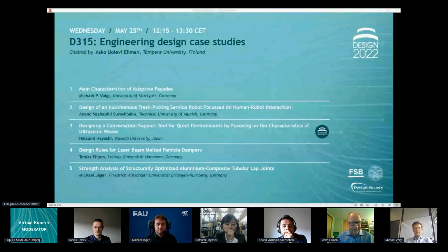Can you explain what is actually the research question of this paper? If you're using CFRP tubes, most of the weight is located at the joints. When you have to join these CFRP tubes together, you have to use a very labor-intensive manufacturing process if you want to laminate them together, or you glue metal inserts in and screw them together. Then a lot of the weight is located at the nodes, which is not the idea of a fiber reinforced truss; you don't get that lightweight.